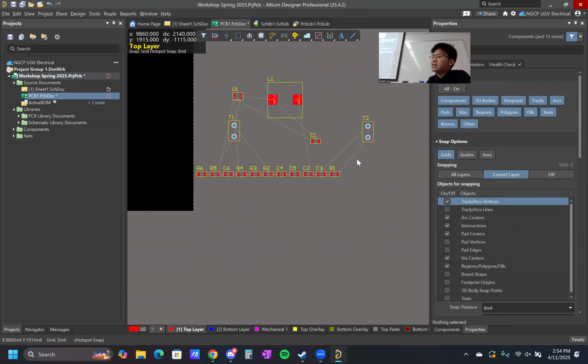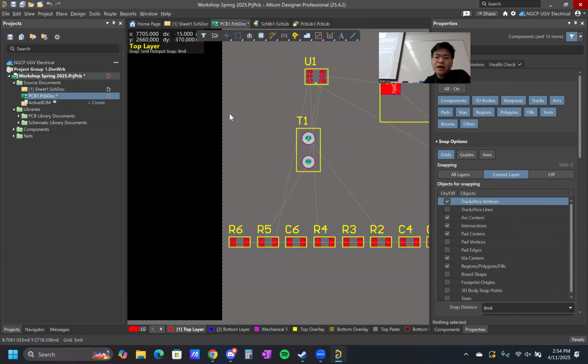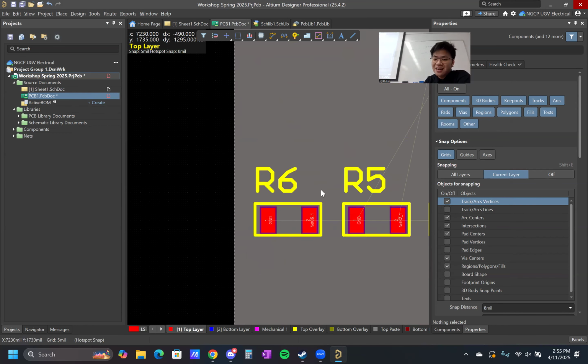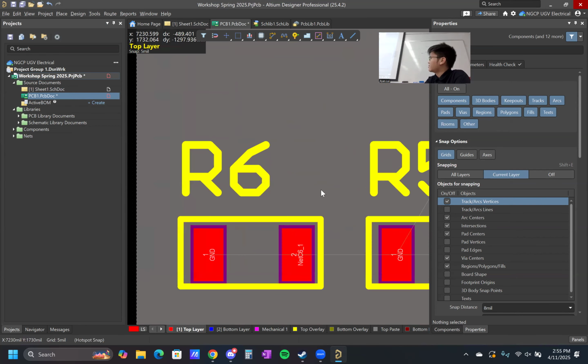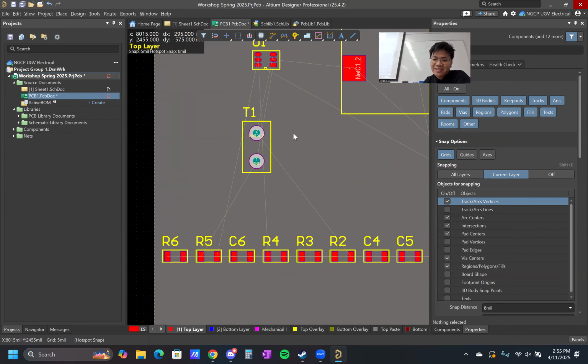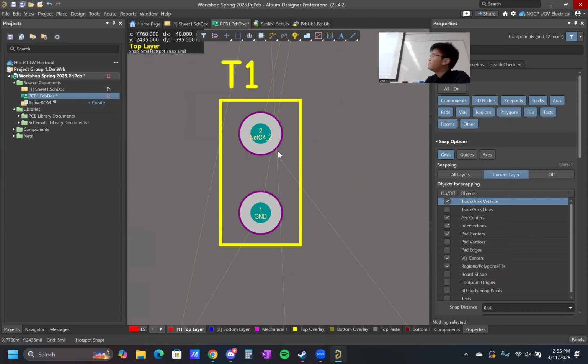So we're going to go into the PCB layout next week. This is really all the steps up to the PCB layout. There's a lot to go over for PCB layout. But you'll notice that these labels have names, and these are the nets that we were talking about. A lot of these resistors already have the ground net label, but these other nets are like a default net, like net for capacitor 4, number 2.